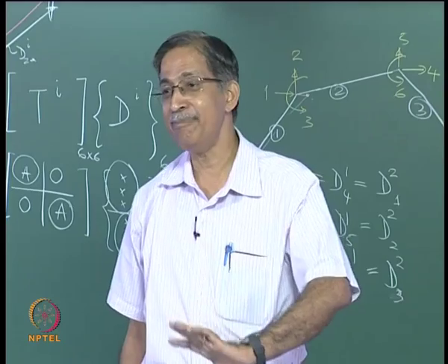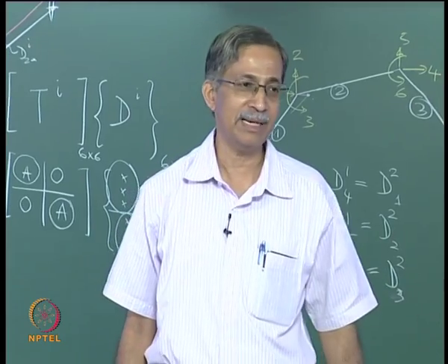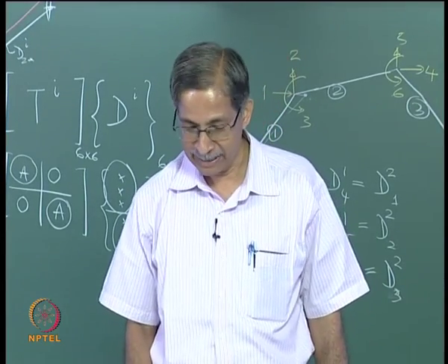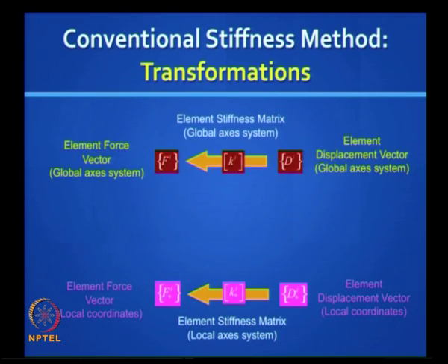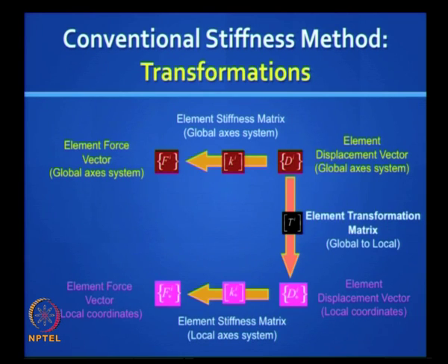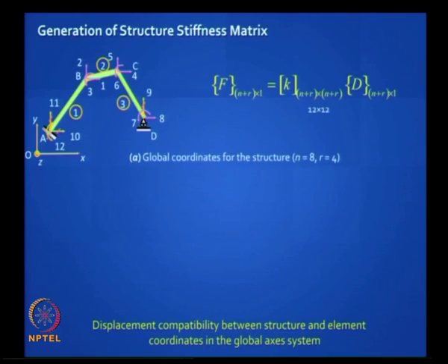This is the first of many diagrams like this we are going to draw in this course, but they are the easiest way of remembering the relationships. Okay, let us play this game once more. We began with this, then we did this, then we did this, then we did this, all 4 are crystal clear. Then we said take the shortcut from di to fi star like that, and then we said my objective is to get this in terms of all the other jokers. So how do I do this? Straight away like that. Got it? That is all. So you have got all the relationships to do the direct stiffness method.